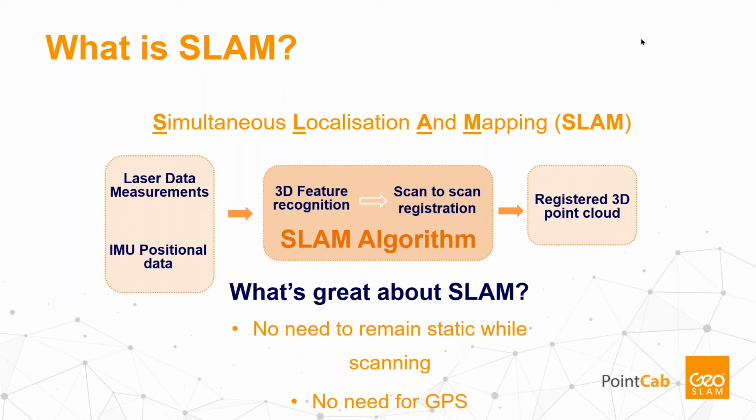And these are the two things you have to compare. You have the single point accuracy from a terrestrial scanner, which is 1 millimeter, and for a SLAM-based scanner, depending on the scan head, it's 5 millimeters to 1 centimeter to 2 centimeters. But then you have the global accuracy, which is the accuracy of your scanner plus the registration, or in this case, of your SLAM and the single point accuracy. And these can be very identical depending on how poorly you scan with a terrestrial scanner. I wanted to add that.